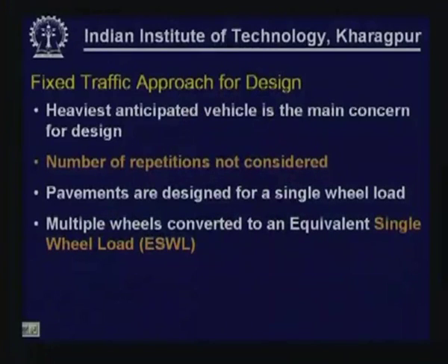So we will be talking about an equivalent single wheel load, and that is the input parameter that we will use for designing pavements for these facilities where the heaviest vehicle is of concern for us. As I indicated, multiple wheels that a vehicle has, of different configurations, will be converted into an equivalent single wheel load, ESWL.